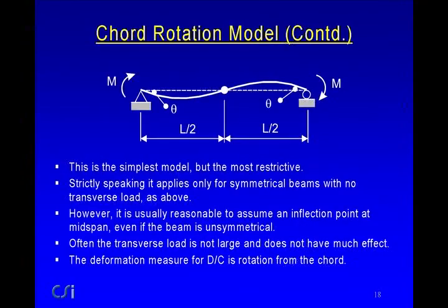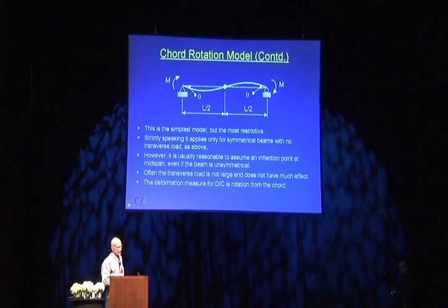So looking a little bit more at the chord rotation model, basically it assumes that the inflection point is at the middle and the moments are the same at both ends. Strictly speaking, it applies only for that case. But you can apply it for other cases.